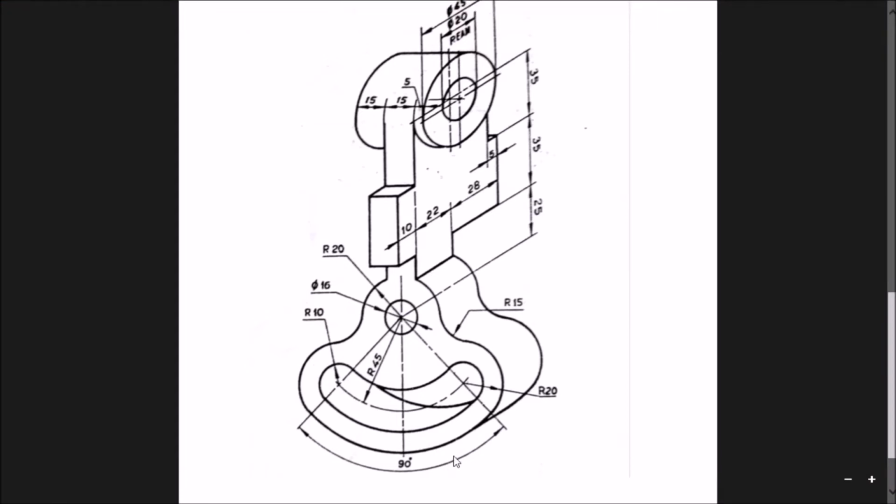This outer part I have to design, and you can see from this axis to this outer part there is a radius of 20. It means from this center point to this outer part the total radius, if I take it, will be 65. So I will select this center point as the center of this outer cylindrical part, and I will design it here.